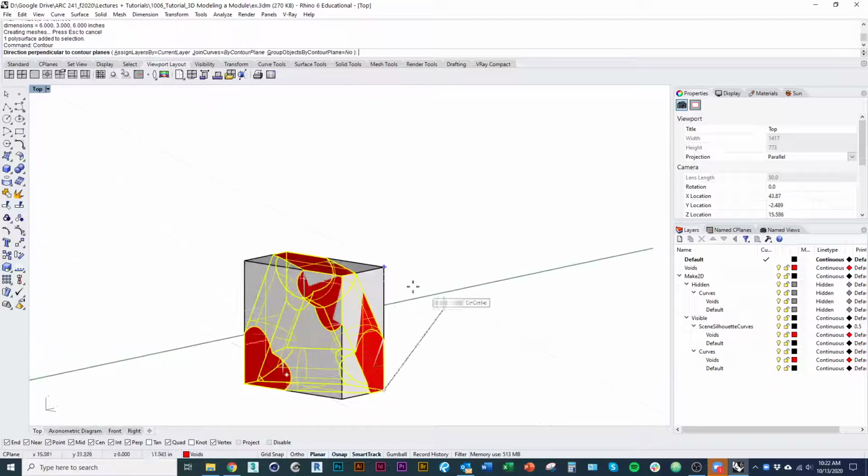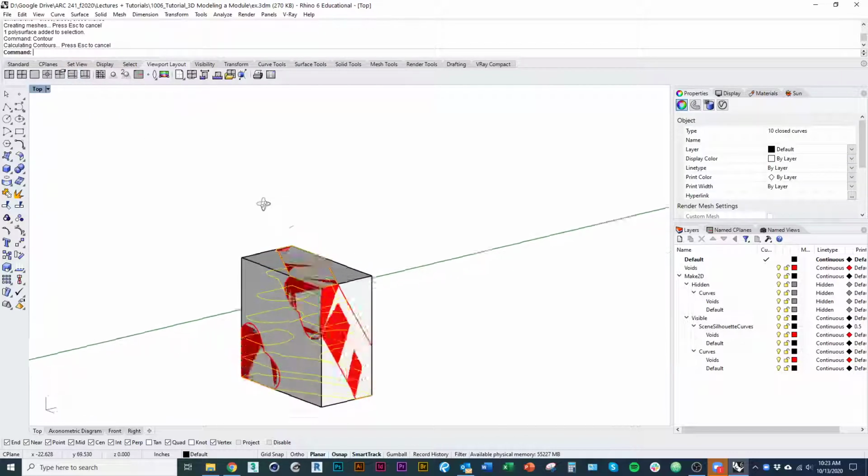Let's imagine I'm doing horizontal contours. I'll draw a straight line up. And this is important. It's going to say distance between contours. And this, you want to put in whatever thickness your material is that you're using. So if I'm using my 1-inch foam insulation, I'm going to leave it at 1 inch. Go ahead and press enter.